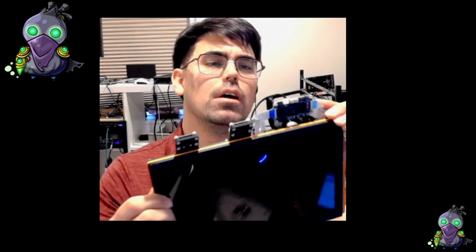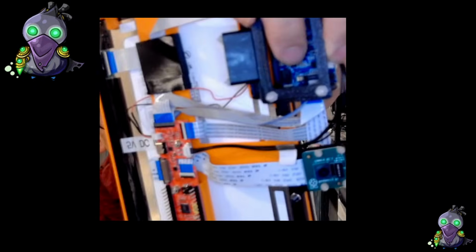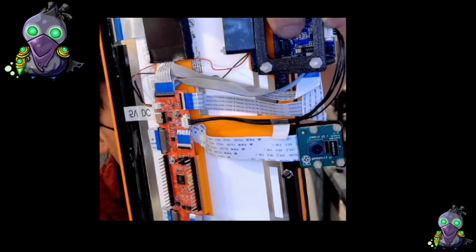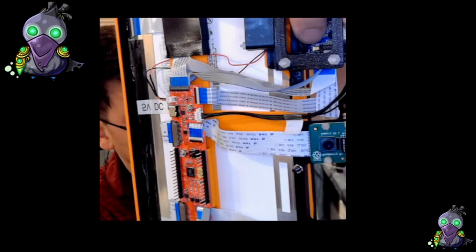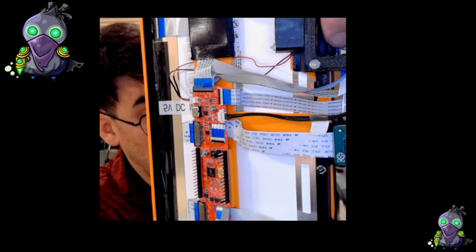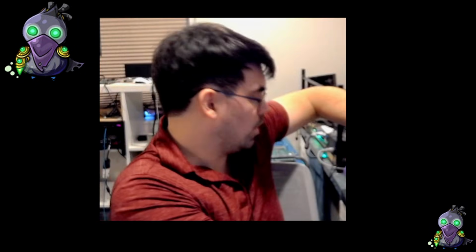To run this in JTAG mode, we're going to change the boot pins. The boot pins are a small little switch. See, right there. Those are the boot pins, the DIP switches for the boot pins. That's going to change between JTAG, eMMC, and QSPI. We're going to set the JTAG mode, and that's in the documentation.